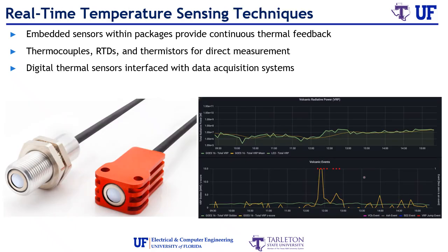Real-time sensors provide continuous temperature feedback during testing or operation. Devices use thermocouples, RTDs, thermistors, or digital sensors connected to data acquisition systems. This enables live temperature monitoring and automatic control, critical for ensuring stability in high-performance electronics.